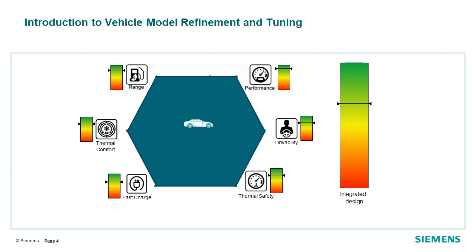Some key areas of modification for tuning of vehicle characteristics include defining the driving cycle used for fuel consumption and range estimation, based on tuning different constants and variables such as ambient temperature, air density, wind speed, vehicle loading, etc. Tune parameters in designing a high-voltage battery to achieve range targets. Regenerative braking strategies to achieve greater range estimation.